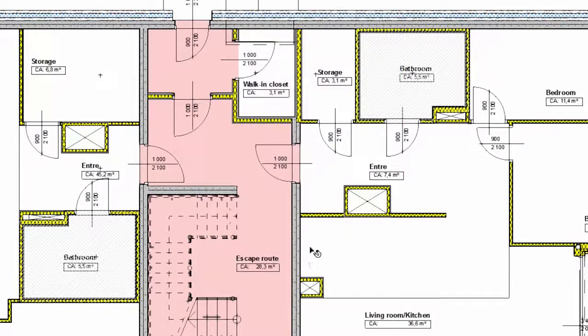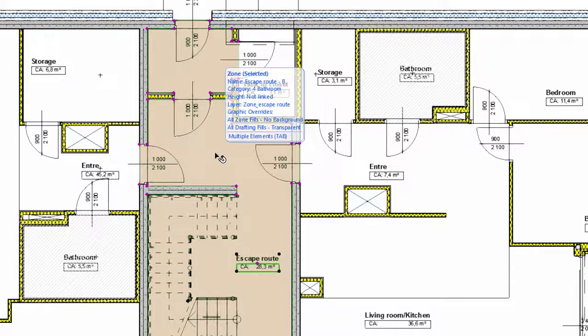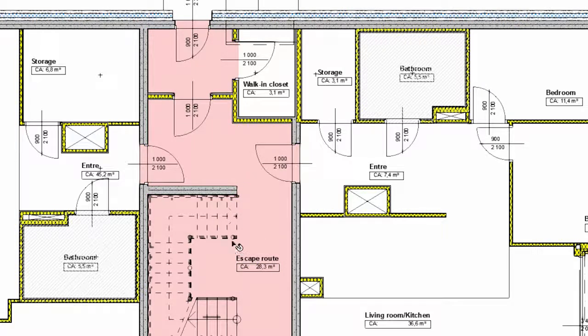We'll use ARCHICAD's 3D zones to identify the doors located along the escape routes. The escape routing zone has also already been created and inserted in the design to the relevant places on all stories. Let's have a look at the floor plans. We would like to create a new property entry for the classification and property data of the zone element. This new property will be used to identify those zones which run along the escape route. Later on, this property will also be used as criteria for collision detection.